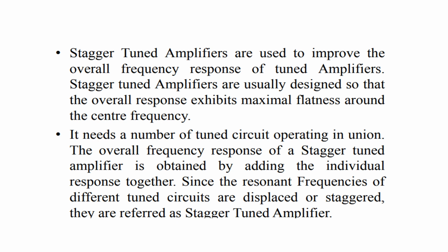As we already said, stagger-tuned amplifiers are used to improve the overall frequency response of a tuned amplifier. The stagger-tuned amplifier is usually designed so that the overall response exhibits maximum flatness around the center frequency. It needs a number of tuned circuits operating in union. The overall frequency response of a stagger-tuned amplifier is obtained by adding the individual responses together. Since the resonant frequencies of different tuned circuits are displaced or staggered, they are referred to as stagger-tuned amplifiers.